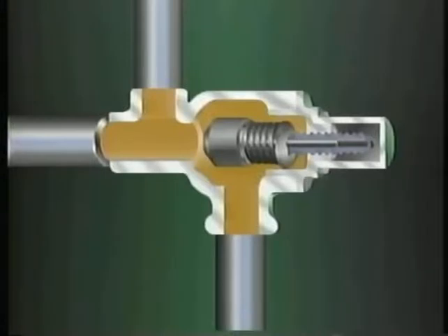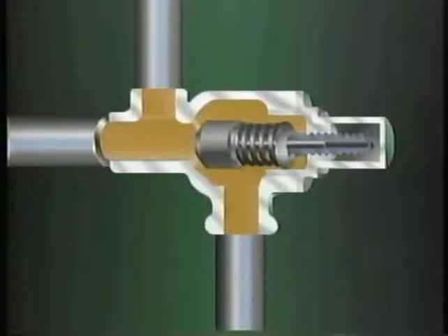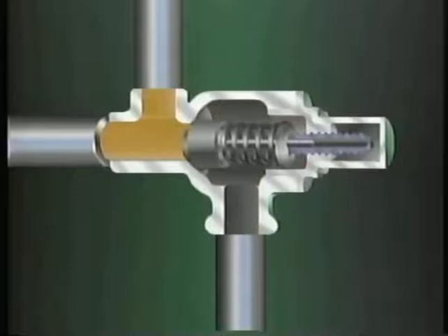As soon as system pressure begins to decrease, spring tension begins to push the disc back towards the seat, and when the pressure returns to below the maximum safe limit, the valve completely closes. While the relief valve we just looked at opens and diverts excess fluid to a reservoir when pressure gets too high, there are other types of pressure control valves that work differently and serve slightly different functions.